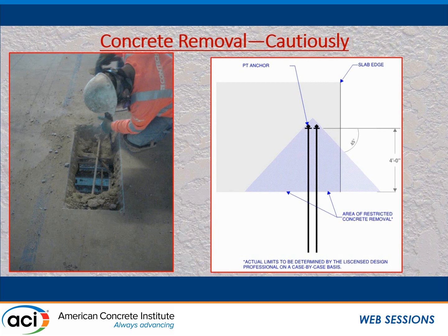You have to be sure that the guys are fully aware of what they're doing, they're properly protected, and you have to always be aware of the bursting zone. You certainly do not want to be excavating on the stressing side or the stress side of the anchor, and open that up, and then you can lose compression, and you got problems. So we do a lot of this and you have to do this if you're going to go in and capture cables to install supplemental or rescue anchors.